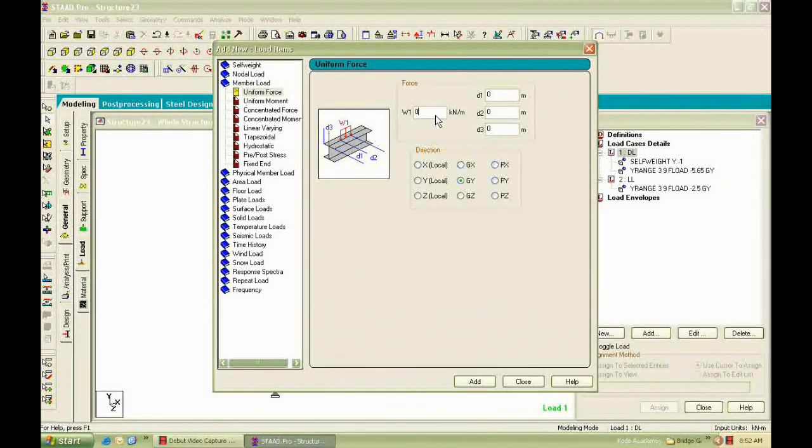Number load. So wall load, if it is 230 thick and if the height is something around 2.5 meter, you'll be getting minus 12 kilonewtons. You can check this calculation. I have assumed 230 wall and 2.5 meter height comes around this value.